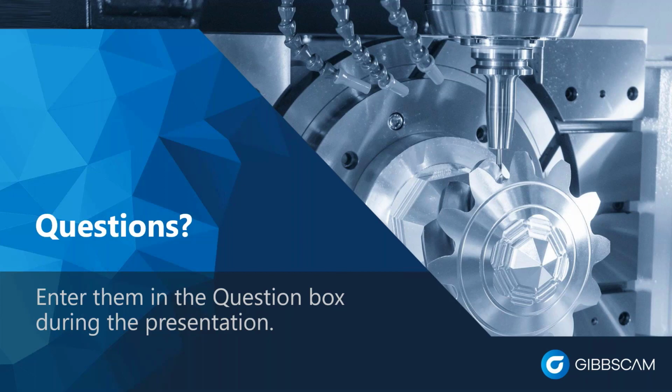Here's another one for you. Does the GibbsCAM 5-axis support TCP and dynamic work fixture offsets, or DWFOs? Absolutely, yeah. The TCP is for 5-axis simultaneous, and as long as your machine supports it, the post and GibbsCAM will as well. And the DWFO, dynamic work fixture, that is for 3+2 machining typically, and yes, absolutely, all our posts support that in 5-axis.